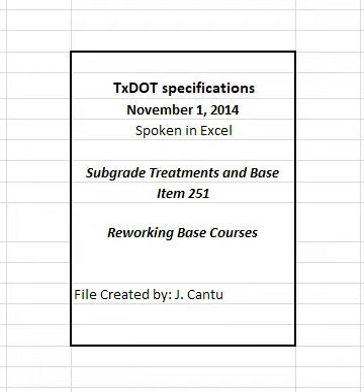4.4 Finishing. Immediately after completing compaction, clip, skin, or tight blade the surface with a maintainer or subgrade trimmer to a depth of approximately 1/4 inches. Remove and dispose of loosened material at an approved location. Seal the clipped surface immediately by rolling with a pneumatic tire roller until a smooth surface is attained. Add small amounts of water as needed during rolling.